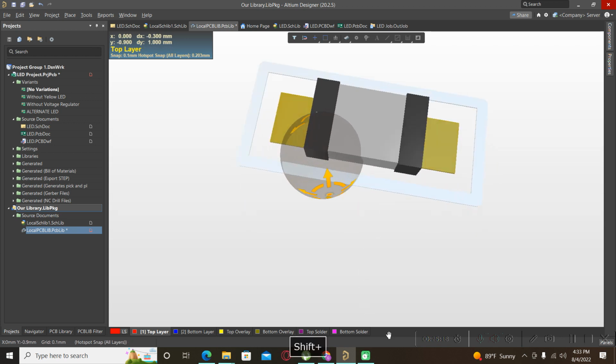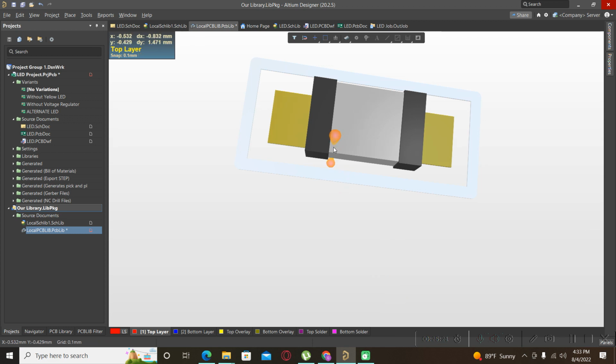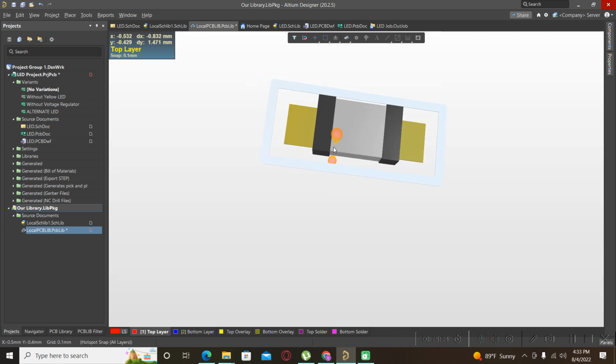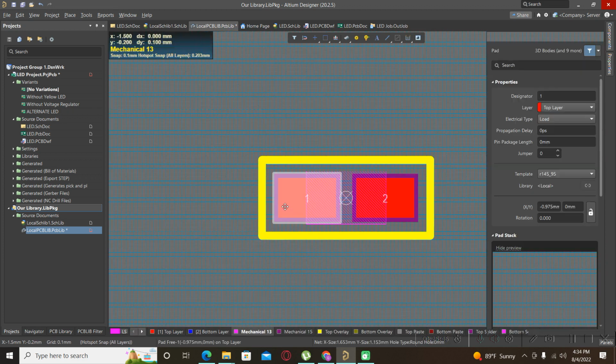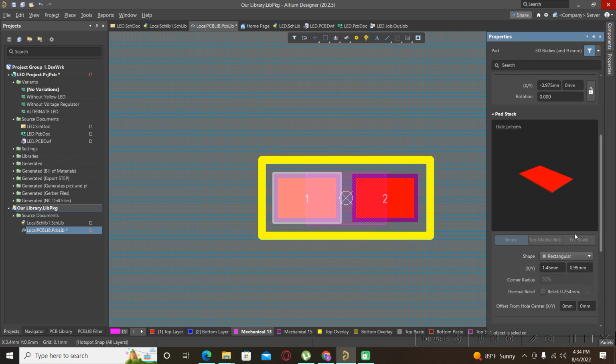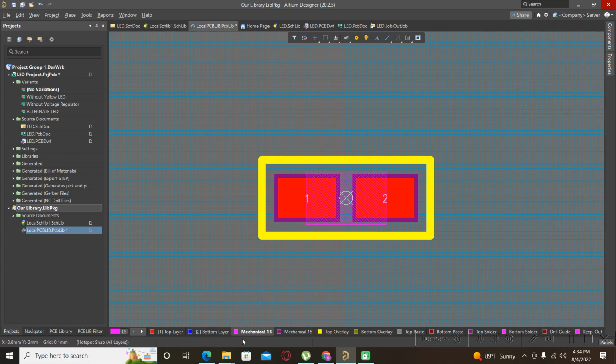Sometimes depends on the requirements, and if the soldering for the small components like 0201 resistor or 0402 resistor, for this custom situation when this will be soldered by hand, we can also create special footprints and we can modify a little bit the length of these pads. And also for this, another mechanical layer will be placed.